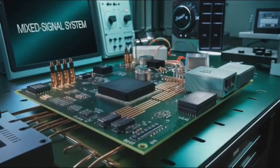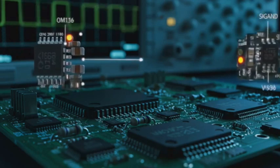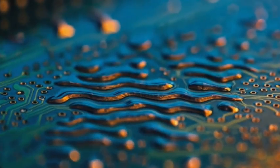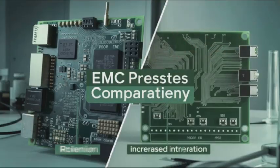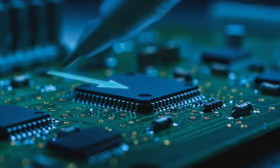Consider this mixed signal system: sensor feeding amplifiers, ADCs, and a microcontroller. Rapid switching transients from digital signals and references typically create noise. Good EMC practices include continuous ground planes, proper decoupling capacitor placement, minimizing overshoot, and isolating sensitive analog signals.